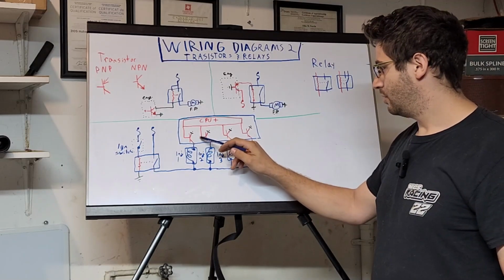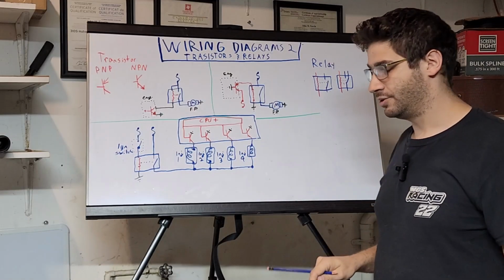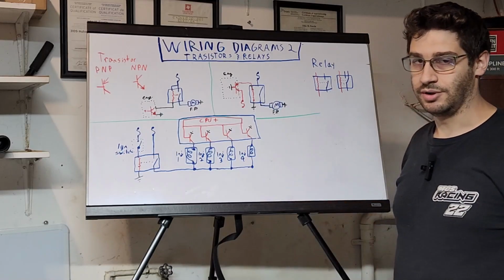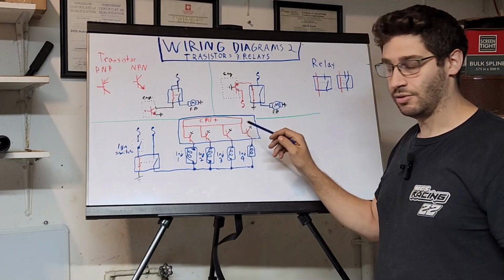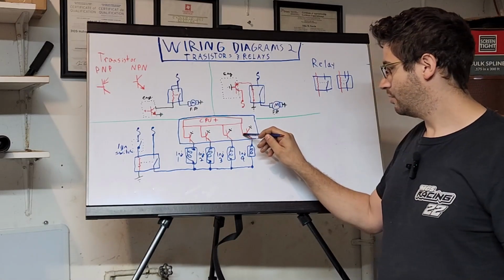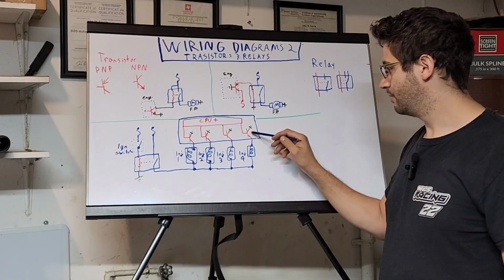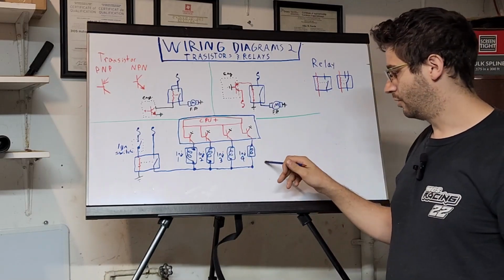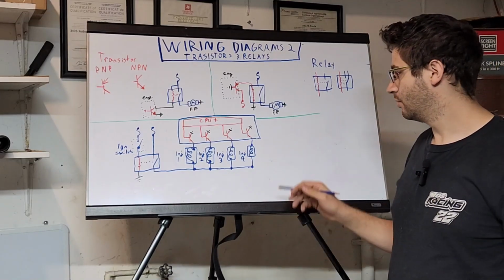Now, the engine ECU is going to want to control each injector, how long it stays open, and when it powers them on individually. So the CPU is going to go and ground the injector to open the injector. It's going to apply power to the transistors, completing the circuit to an internal ground within the ECU, firing the injectors in the firing order, holding them open for whatever amount of time, depending on engine load, engine speed, whatever.